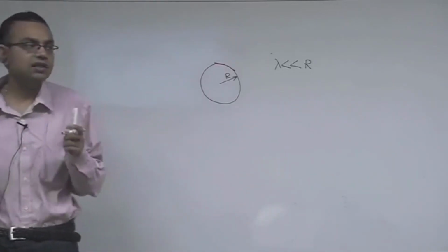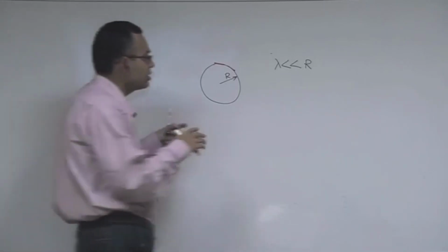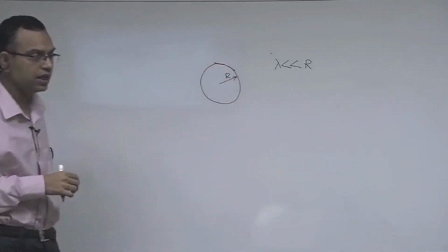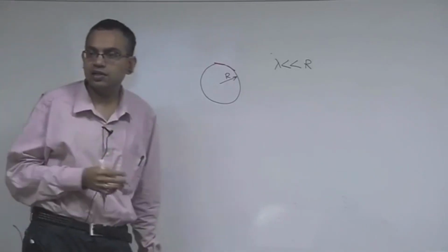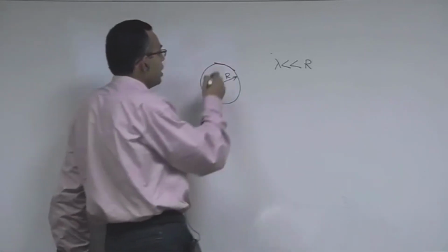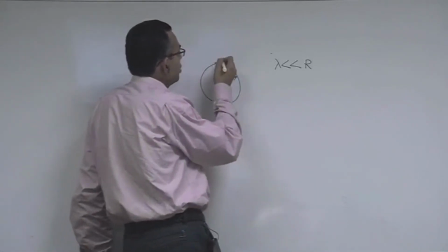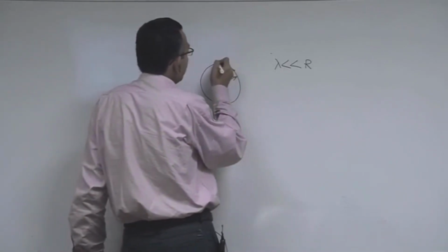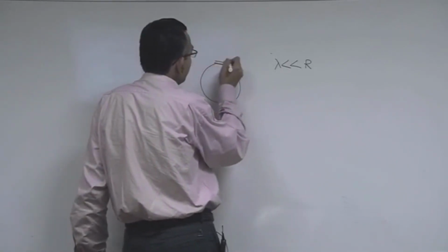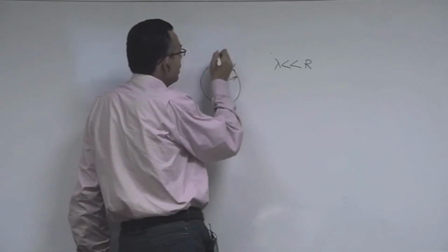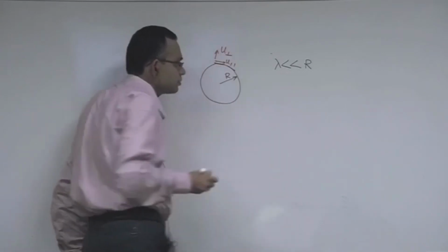It is not that it is a flat plate, but because the radius of curvature is large, you can consider the particle as a localized flat plate with local parallel and perpendicular velocity components, u parallel and u perpendicular.